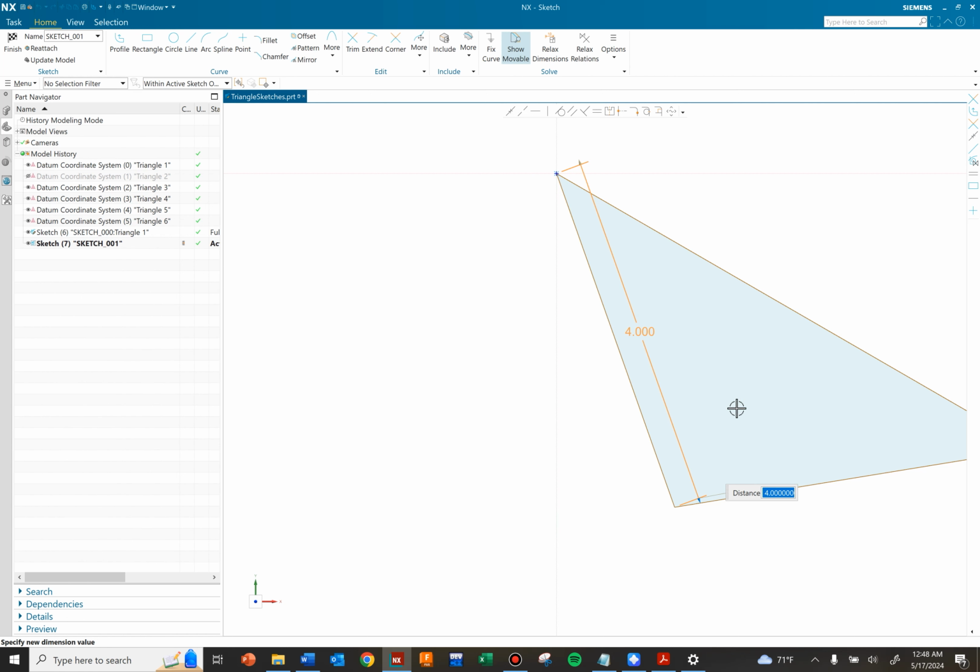And now I can actually edit this and put in a dimension. So if I put in 3.837 and hit enter, it's going to tell me that you're adding a dimension for the first time in the sketch and ask if I want to scale everything. This is really helpful because let's say we drew this like 30 inches for some weird reason, and we need to scale.